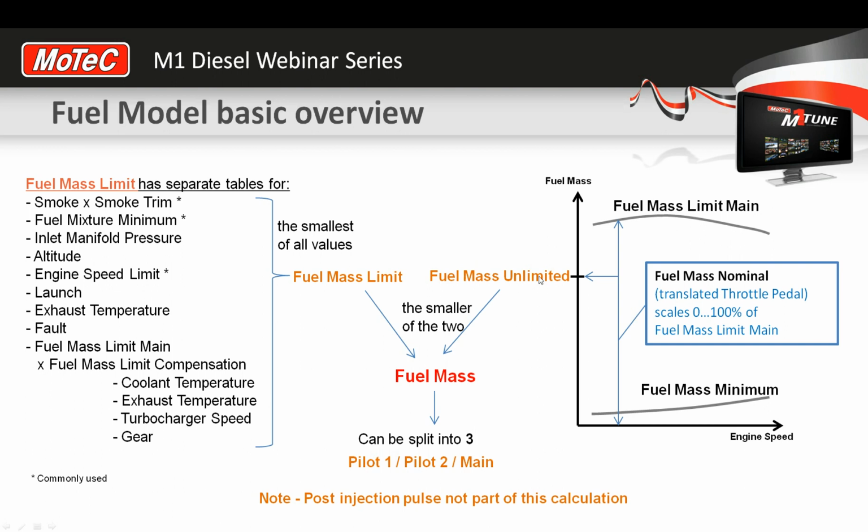Now that heads off down to our final fuel mass that's going to be delivered to the injectors. As simply as configuring these two tables, the throttle pedal table, you can drive that engine straight away. If it's a bit smoky, you take your foot off and it won't be so smoky. You can virtually start it with some basic configurations and drive it straight away, and as long as you regulate the amount of fuel with your pedal to make sure you don't get too rich, you can drive it around the block within 2 minutes of configuring it.